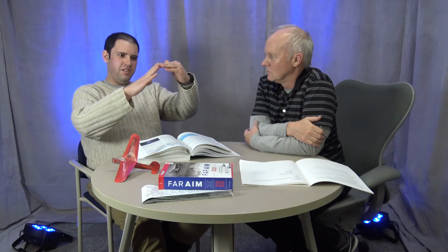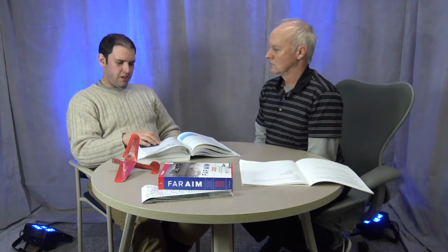Because the whole tail is moving, rather than only half the tail moving, which creates some amount of turbulent airflow, if the whole tail moves, that keeps the airflow nice and smooth. It's more efficient, helps it to go faster, but it's heavier. So that's something that designers have to balance: do they want to use an elevator, which is lighter and simpler, but creates a little bit more drag, or do they want to use a stabilator, which is heavier, but creates less drag?